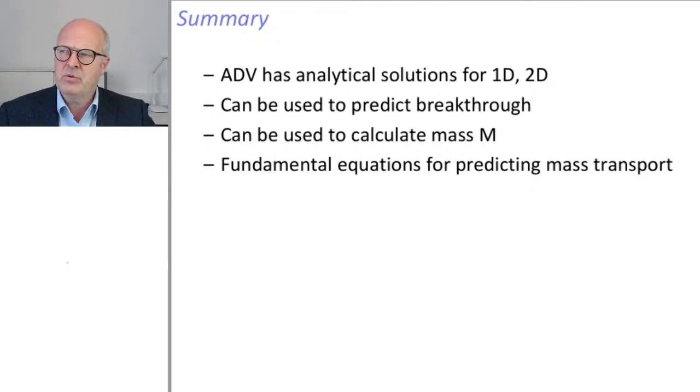Now the analysis of fluorescence is not difficult, but there is still a laboratory cost of usually 10 euro. Some offer it for 5, but this is not sustainable. 15, 20 is higher end. But still, with 200 samples, you will finally have a cost just for analysis of 2,000 euro. To write the permit, 1 day of work in an engineering office is almost 1,000 euro with some extra work before and afterwards. So you're already at 3,000. Then you have devices that you need to have or lend or refinance, and you need to buy the tracer. So you're at 4,000 or 5,000.